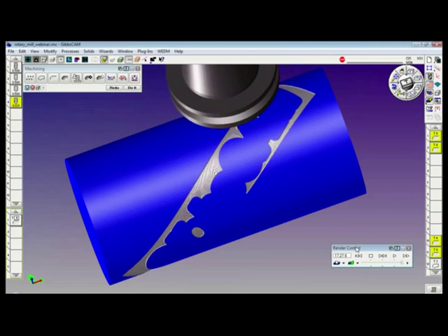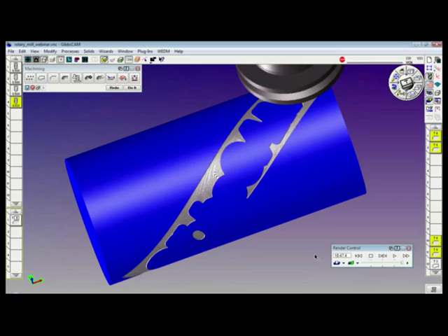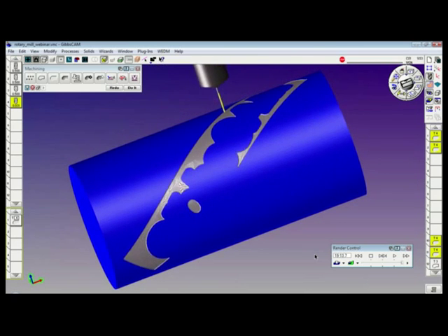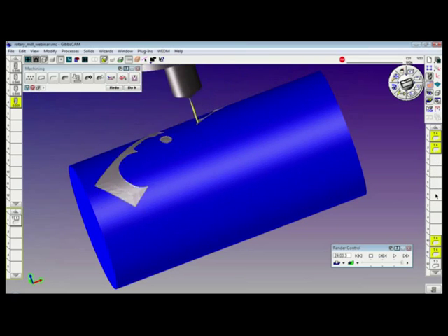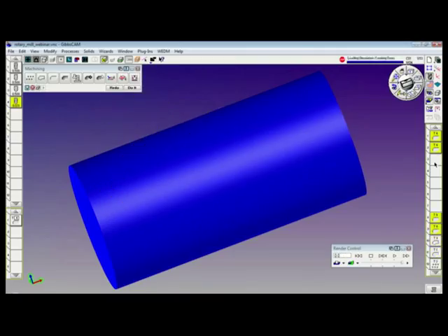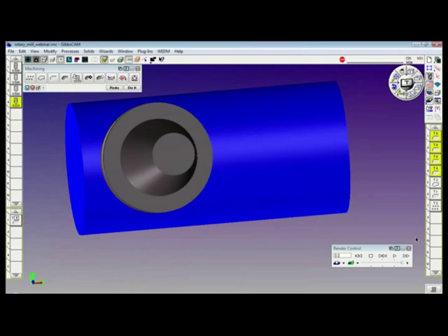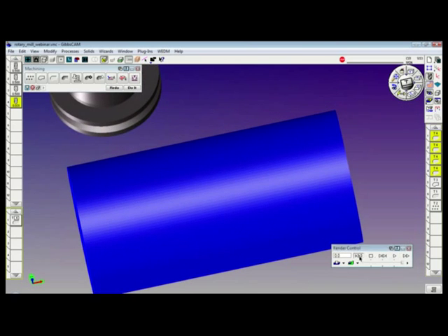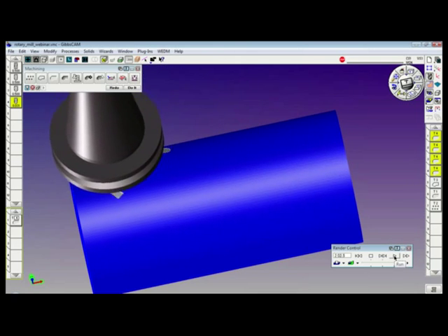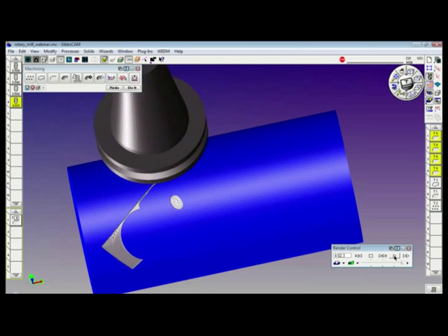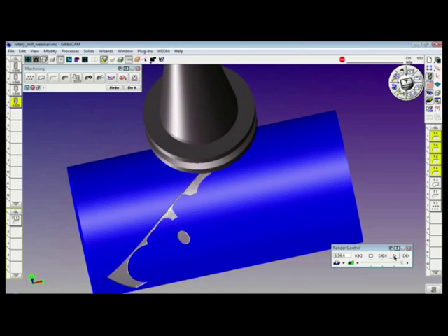It'll take a moment because we've got a very fine step over, and I've got the rendering turned up all the way. While this is happening, you notice that there's a series of empty spaces along the completed operation tile list. If I hold the shift key and double click an empty tile, it pulls up the operations that are down below. It also restarted my rendering because I was picking unselected ops. I was clicking on empty tiles and there's no ops selected.